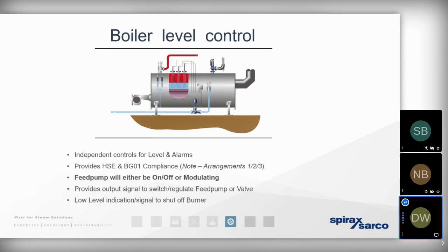So if we're calling for a mass of a much lower temperature water from the feed tank, if the boiler's operating at 10 bar gauge, for example, the boiling point is 184 degrees. So if we're calling for water from the hot well at a very low temperature, could be 50 or 60 degrees, then you can appreciate that that's going to have a significant quenching effect. The rate of steaming is going to fall off. The boiler is going to use a lot of energy to race to start to produce steam again. So there's an energy inefficiency. And the steam that is going to be produced in those first few moments, it's going to be relatively wet, contributing to that erosion, corrosion, and water hammer that we spoke about.